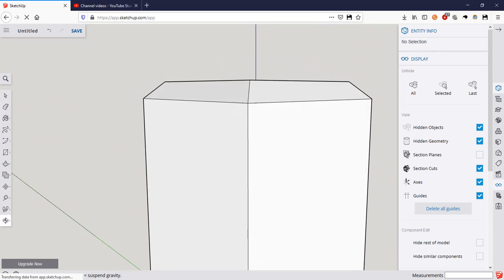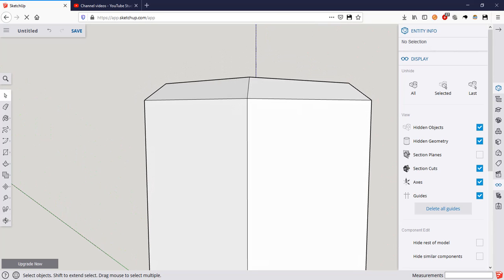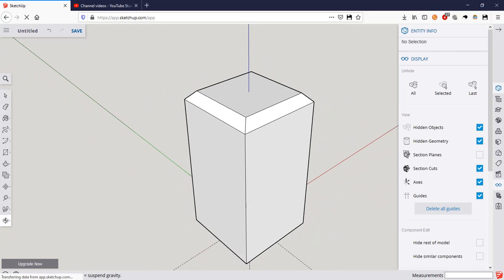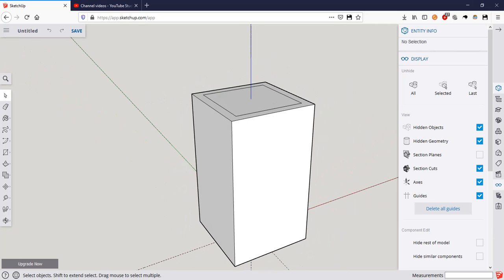So now we got this 45, and how you know it's 45 is because our offset was 5 millimeters in and we went up 5 millimeters, so that means 5 and 5. So that's when it comes to triangles and math. If you have two equal sides, it's a 45-degree triangle. So kind of nifty, but let's go ahead and back the offset off.